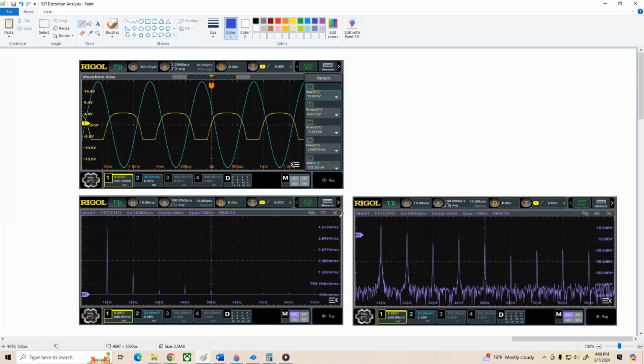Before we go on, I just want to mention that the input voltage I used to overdrive the amplifier was about 150 millivolts peak to peak, and the resulting output is what I used to experimentally determine the clipping points of the amplifier.